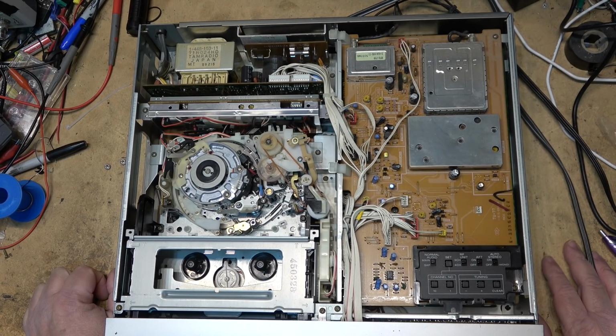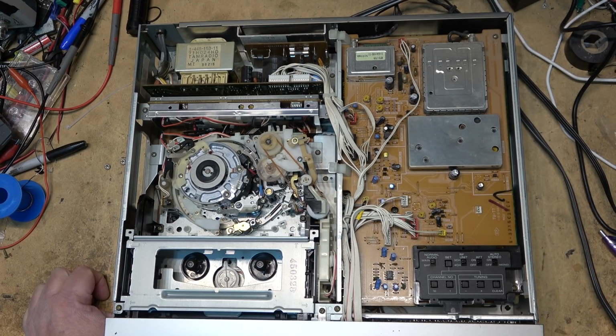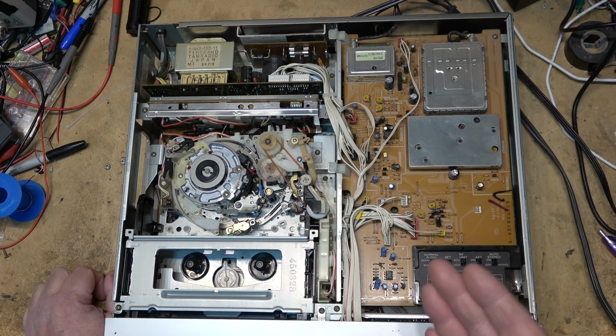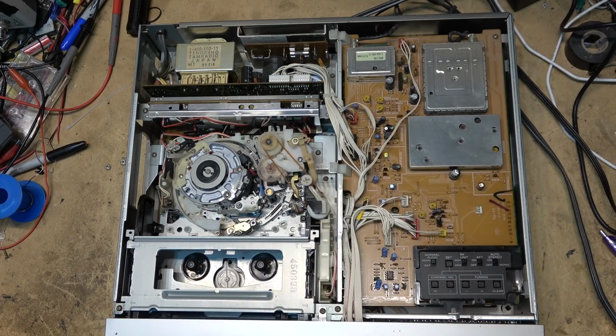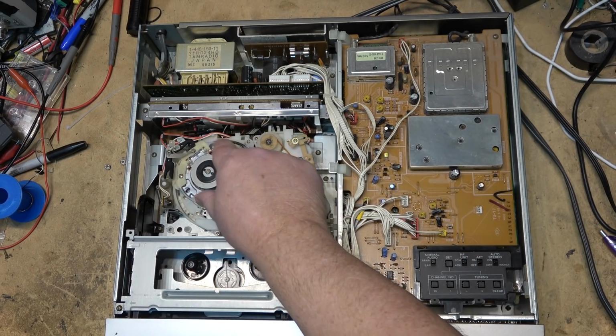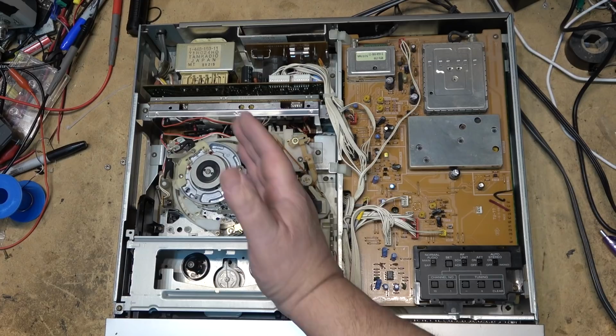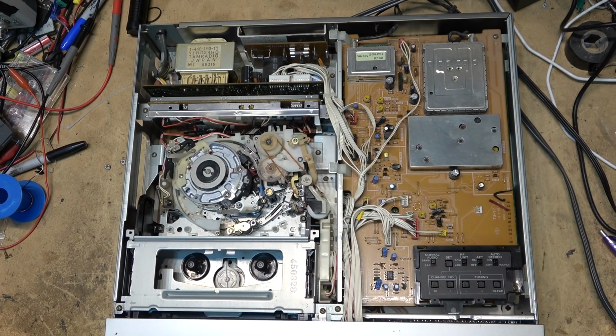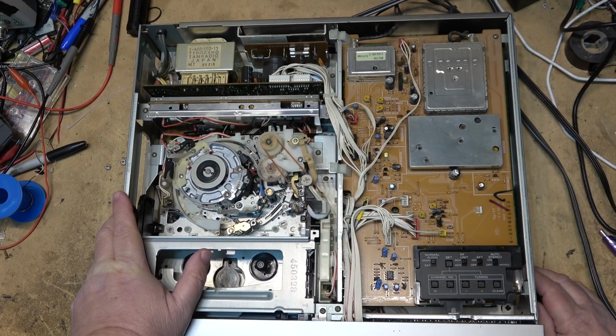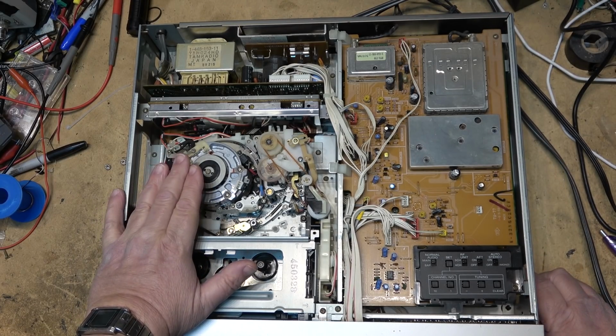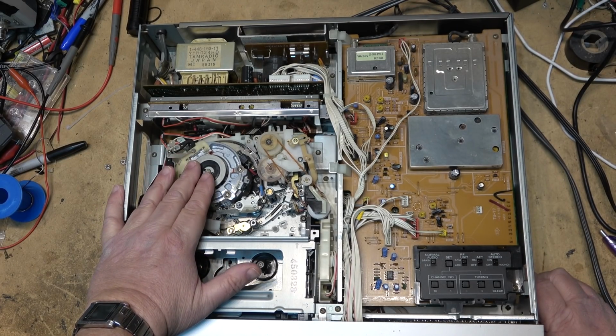So the plus 7 head would have a minus 30 degree offset for its audio pair, and the minus 7 head would have a plus 30 degree offset, or in the case of VHS, 6 degrees on the video head. But that gave a 36 degree difference in the angle that the signal was recorded to the tape. The audio was recorded first on a leading pair of heads, and then the video was recorded over top of it, which would erase some of the audio signal, but there was enough there to be recovered by the audio head on playback.